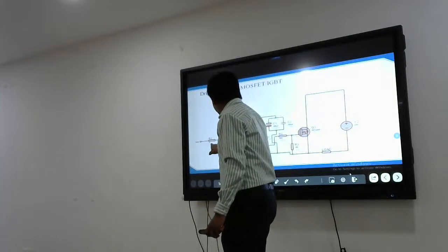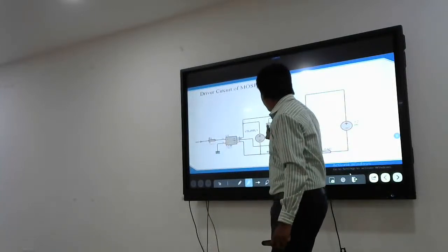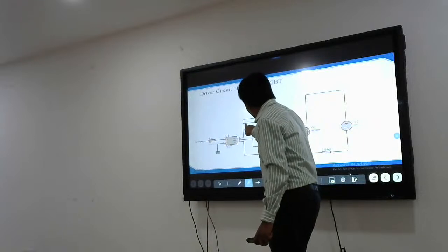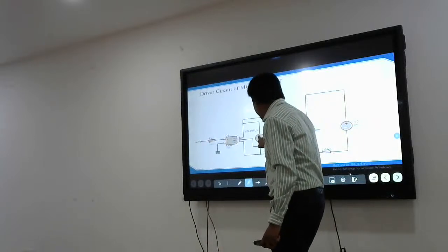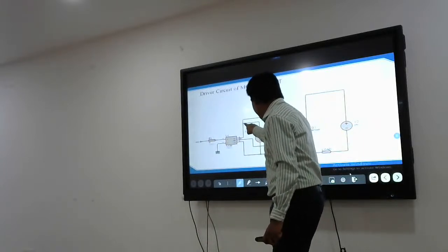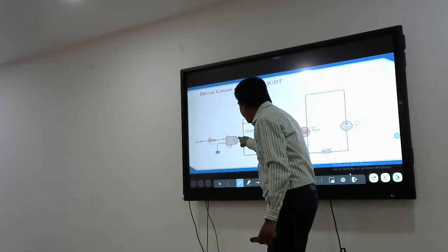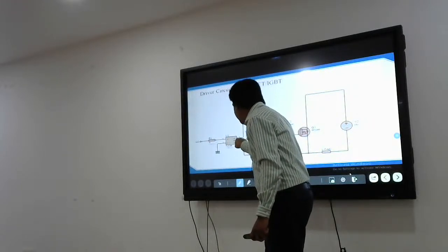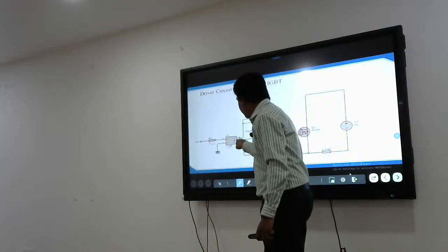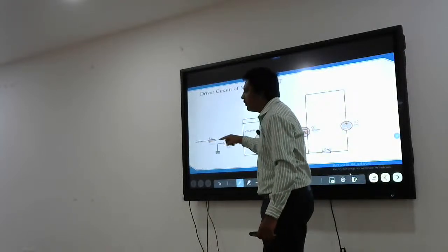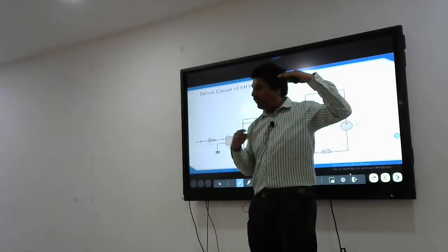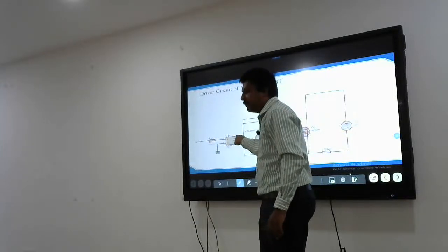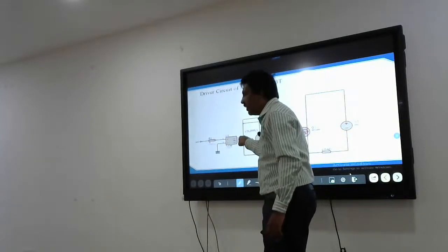Then if this is on, this circuit helps us: you see plus 12 volts is here. This 12 volts comes to the 8th pin, which is directly shorted to the 7th pin when it is high. That means at the 6th or 7th pin of this TLP250, if it is 3.3 here, it is 12 volts there. If it is 0 here, it is 0 there.